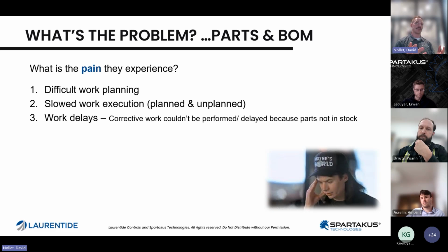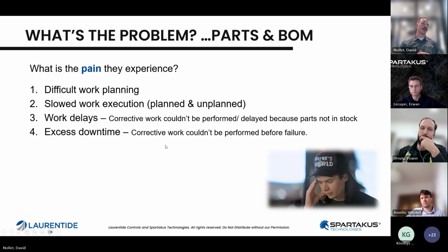Well, now I can't do that job right now because I don't actually have the bearing that I thought I had. So I couldn't do that intervention when I needed to, and now I don't make it to the next down day, and now I have a failure. I end up being in reactive mode, even though I was doing my vibration analysis to avoid being reactive. Because I mismanaged my parts and my BOMs, I am in reactive anyway.